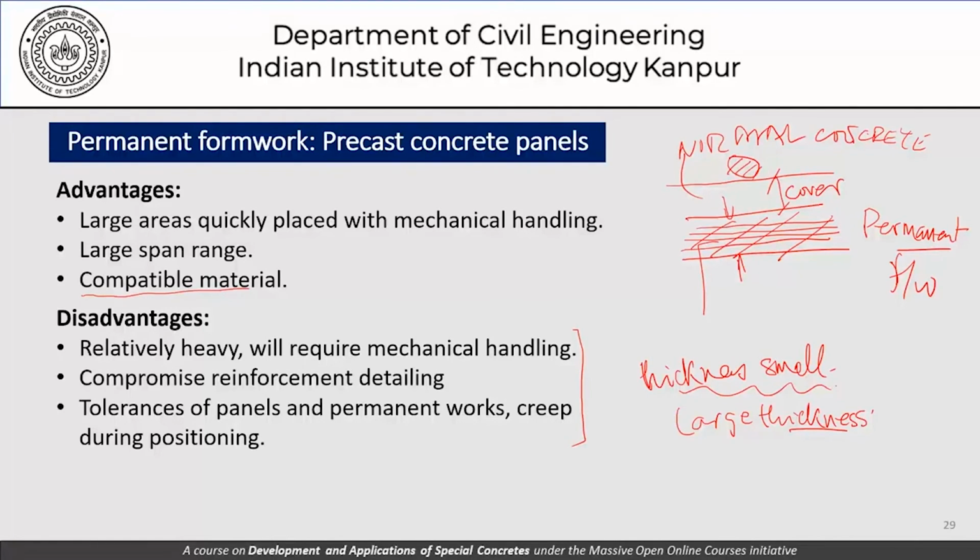So to explain this concept once again with an illustrative numerical example, suppose we have a 500 mm thick slab which we need to cast. So this is 500. Now if the formwork thickness, or the permanent formwork thickness, is just about 20 mm or 25 mm, and the rest of it is being cast in situ, then the thought process would indeed be that yes, there is a 20 mm formwork with 480 mm in situ concrete, and the total thickness of this member is 500.